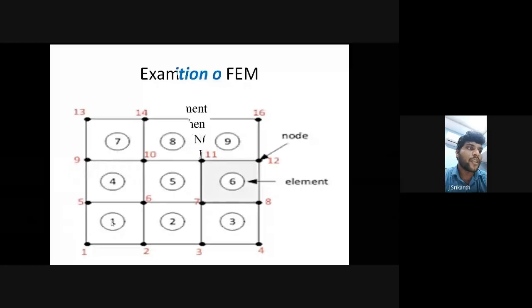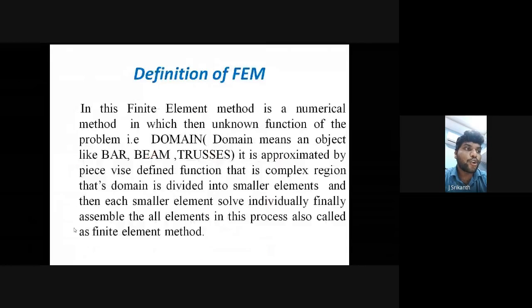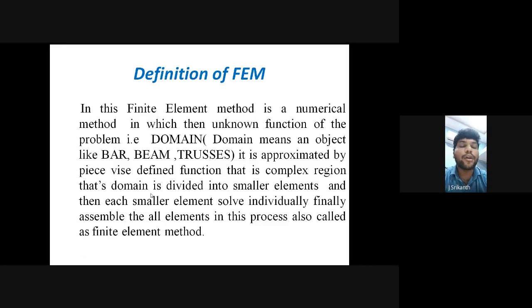So the definition is: the domain is divided into smaller elements. The whole structure, the whole wall, will be divided into smaller regions or smaller structures. And then each smaller element, that means each smaller brick, is solved individually.